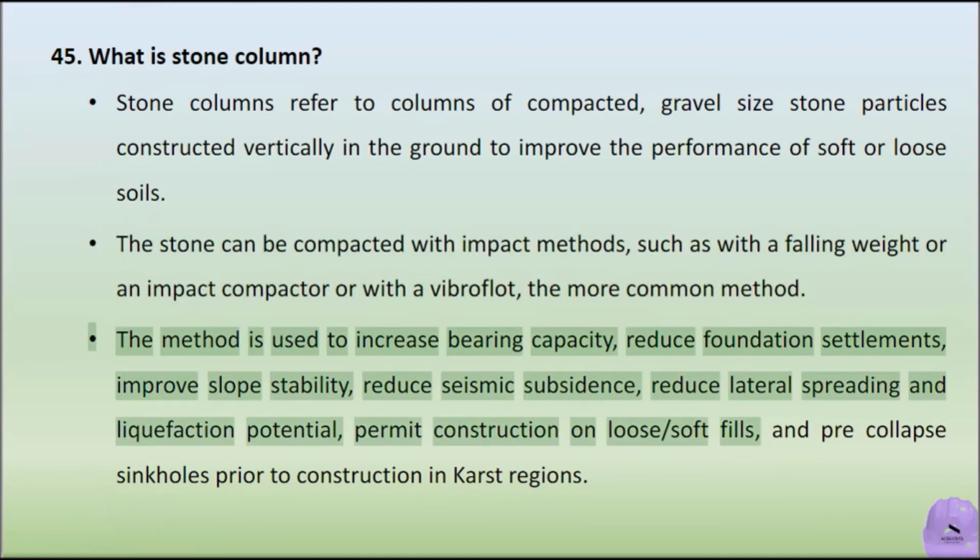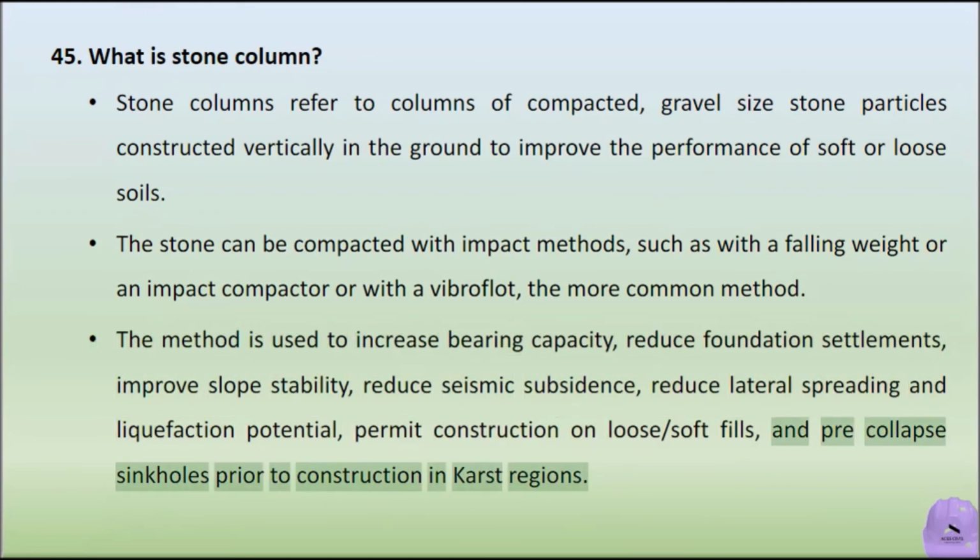The method is used to increase bearing capacity, reduce foundation settlements, improve slope stability, reduce seismic subsidence, reduce lateral spreading and liquefaction potential, permit construction on loose soft fills, and pre-collapse sinkholes prior to construction in karst regions.